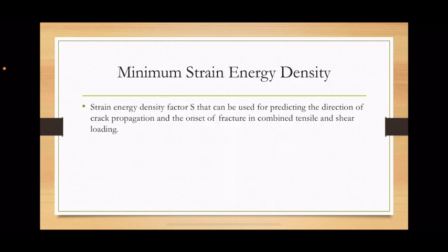So for the minimum strain energy density, the strain energy density factor can be used for predicting the direction of the crack propagation and the onset of fracture in combined tensile and shear loading.